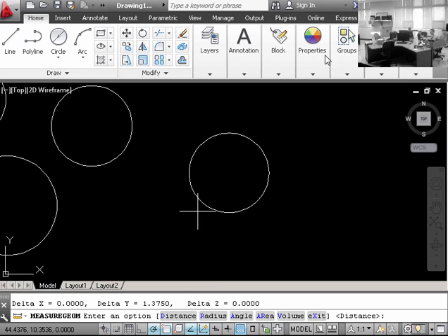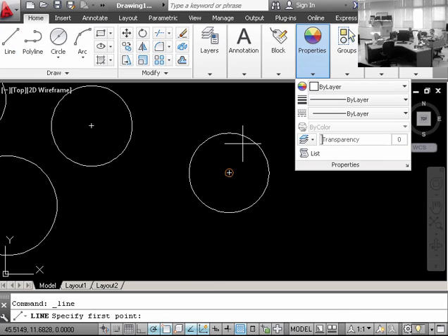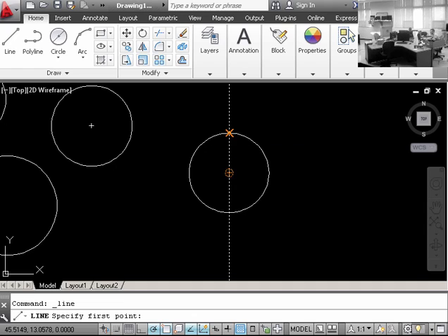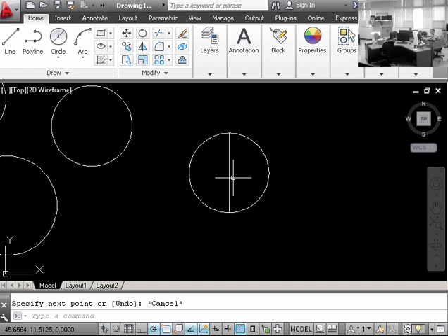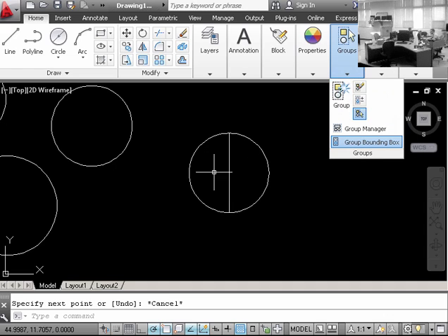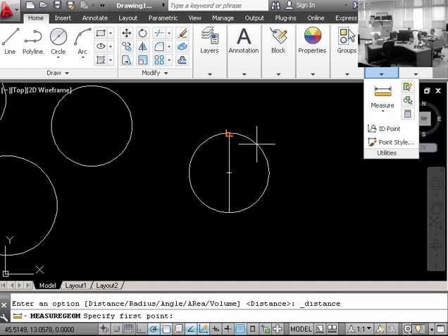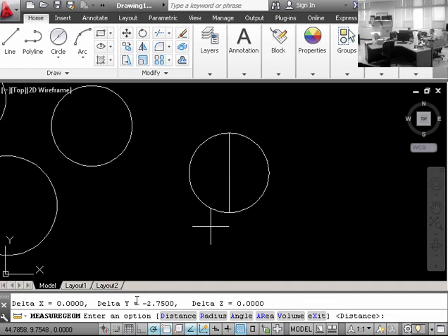By the way, when you want to use the measure tool, or the distance tool technically, the measure is actually the distance command. It likes to click on stuff, and if you can't find a way to click on it, you can always draw lines in. Hit your tool, click on one end, on the other, and it gives you the distance between 2 points.